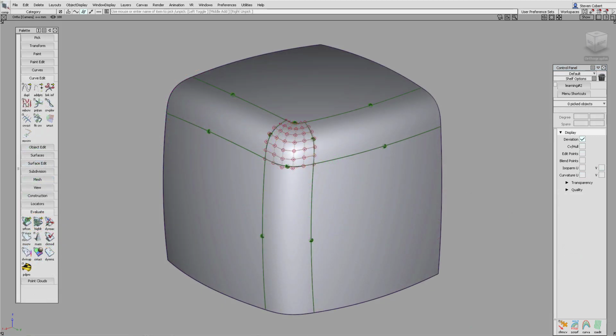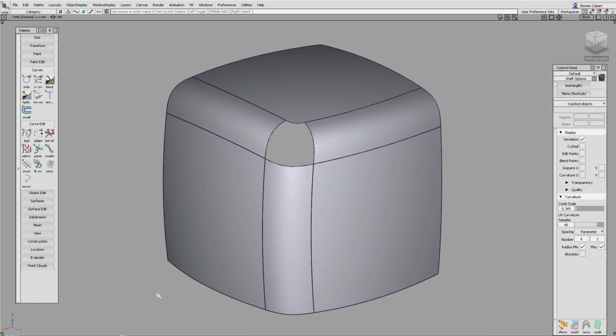We're going to make the corner surface by firstly creating the hole that the corner sits in. We'll then build a surface using square. If we try to do this with the trimmed fillets, then we get a very bad result. It's always better to do this with the trim converted fillets. So what we need to do for A-class work is to keep the trimmed surfaces in the final model, but we'll use a trim converted copy as a construction surface that we can use to actually build the corner.